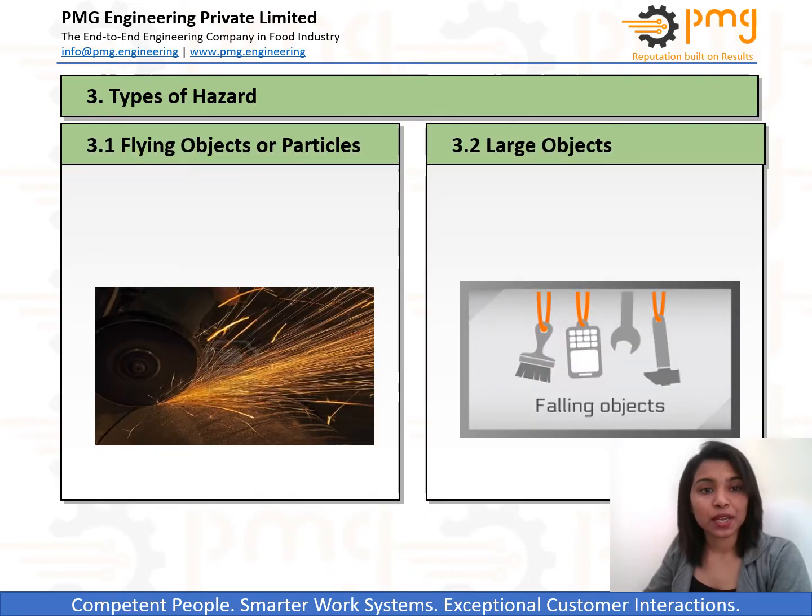Apart from potential hazards, here we will be talking about some types of hazards that are very commonly found in any construction site. Operations such as sanding, grinding, welding and lathe operation produce dust, vapors and flying particles. To protect other workers, work area barriers such as movable screens and barriers should be set up to separate workers and bystanders from hazardous operations.